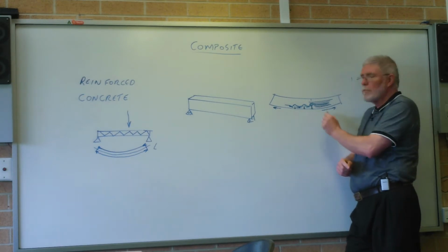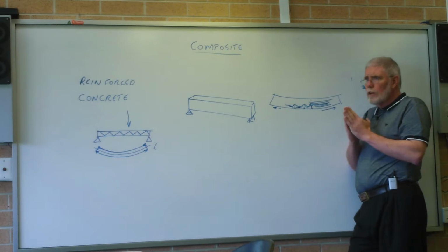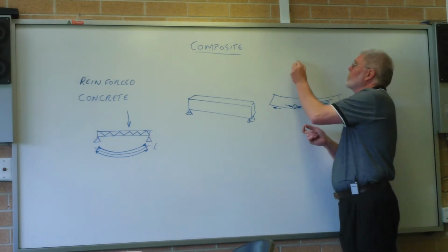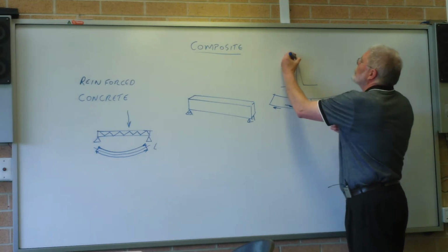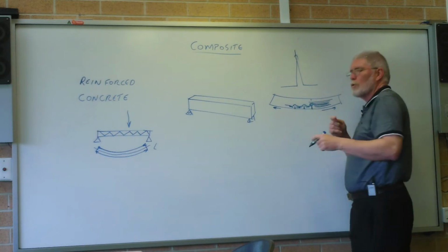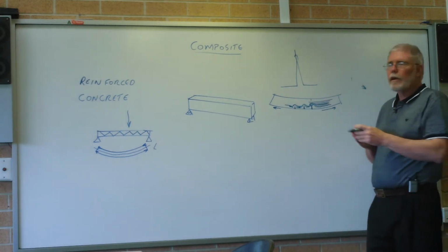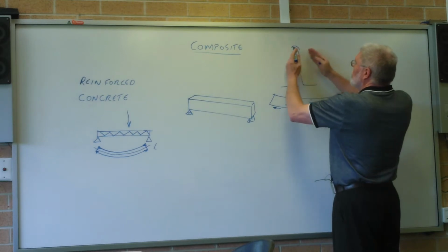So as we get to that place where the tension stress starts to get large, as you pull it apart, the stress raiser here cracks it even further. And that crack, it's known as crack propagation, gets more and more stress concentration at the top as you get wider and wider.